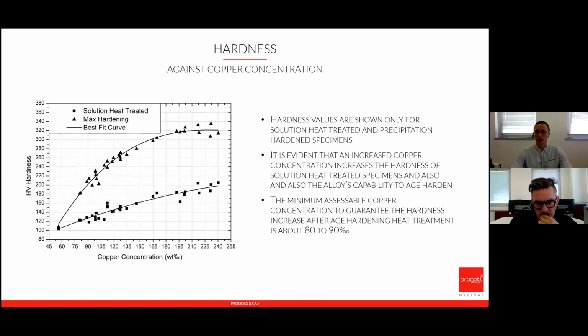but there are some pieces of advice on how to deform the material. For example, in pipe drawing, it's important to maintain a specific ratio between the internal and external diameter, so as to decrease the thickness of the tube in a certain way, because drawing is a very stressful process on the material. It's important to avoid going over the maximum cold working that the material can support before the annealing. And there is a lot of little advice and little tricks that you can apply in order to get the best result possible.